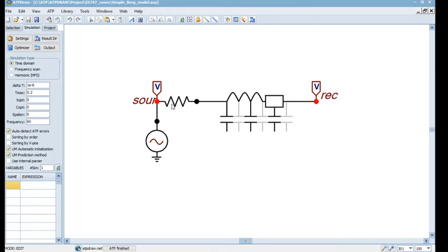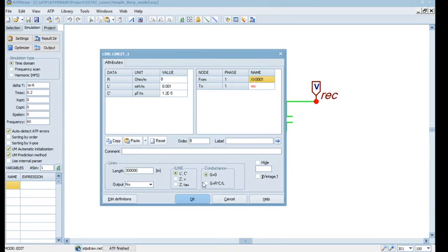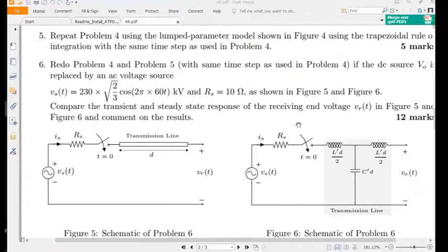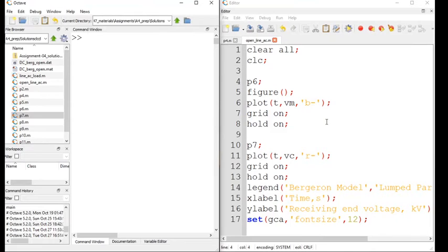but it really doesn't matter here, right? Whatever voltage you impress here, the current which comes through will be negligible, so the receiving side will be higher than the source side for this 300 kilometer line and the specifications you have used. And for example, let me show you, if you want to relate this with the already known waveform, a simulation experiment.